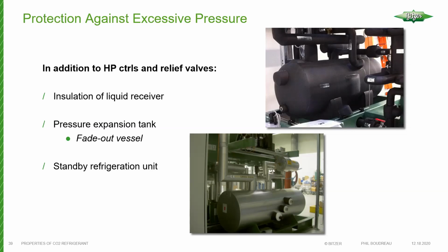So another approach, and this is used typically on supermarket systems, in fact, would be a standby refrigeration system. And if you don't have these approaches, then the system needs to be able to withstand the highest ambient temperature that it's going to be exposed to without causing any problem. But you still need to have the relief valves and everything, and the relief valves are there to limit the pressure of the system to the lowest pressure capable component. Okay, this is the way it has to be so that nothing can rupture.